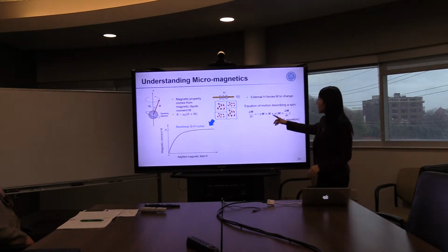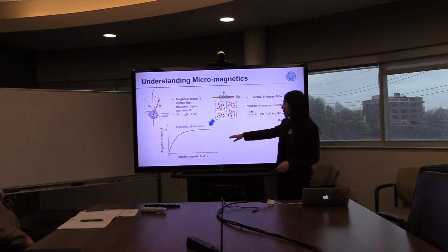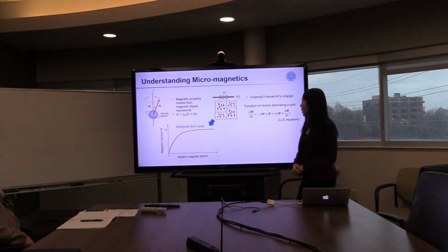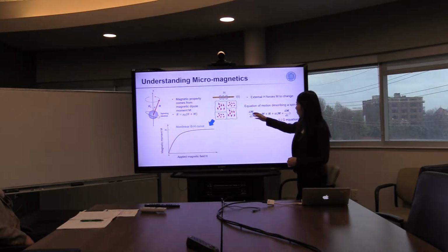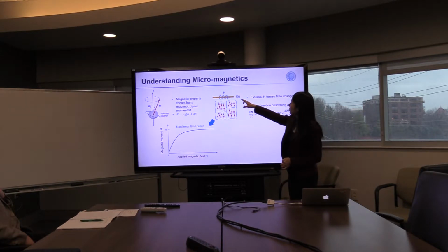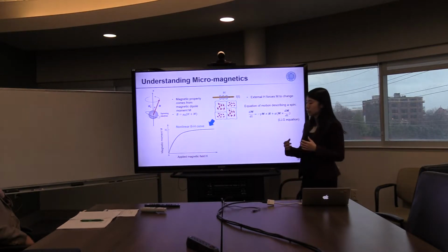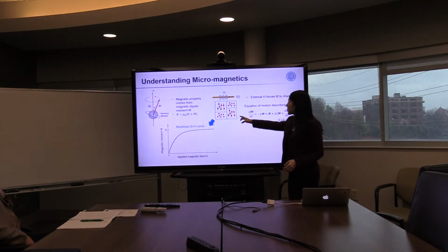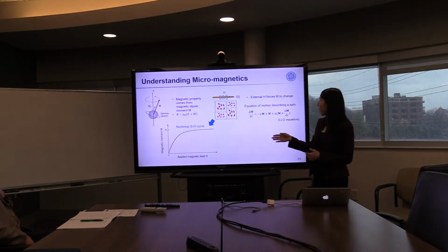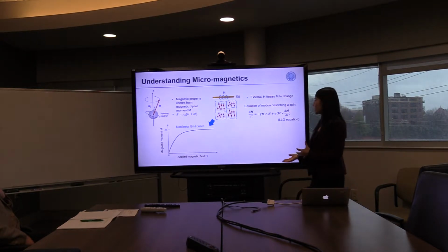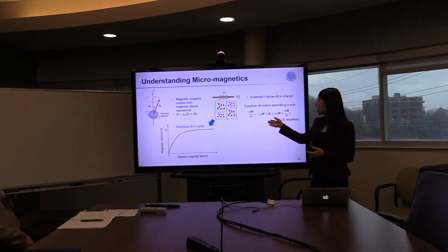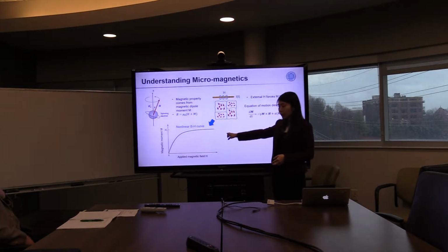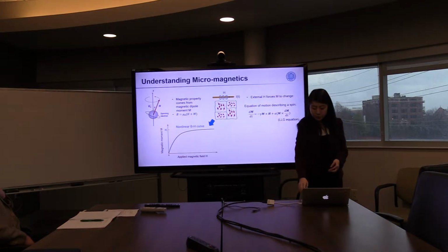And this actually is the answer why we have a nonlinear BH curve. Basically, when the external H is large enough, these magnetic spins can no longer be aligned. There are no more spins to align, and the rotational behavior stops. So that's why we see a saturated behavior.